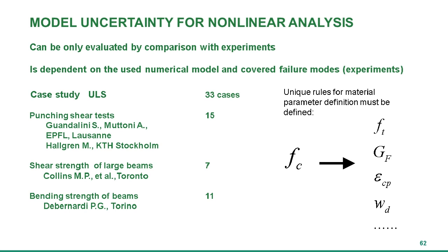A very important thing for these evaluations is to have a clear definition of the input parameters. You have to understand, and maybe some of you have used nonlinear analysis, so you know that there are usually many parameters, but as engineers, we usually know only the compressive strength. So it is important that there is some clear set of rules defined for how all the other parameters are estimated from compressive strength. And if there is no estimation or no clear rule given, then some default values should be used in the whole study.